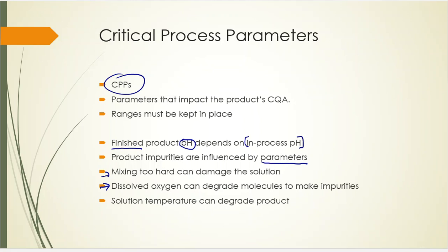And the reason is because that DO, that dissolved oxygen, can actually react with some of these APIs that we are after. And that DO, if it reacts with the API, can inactivate it, or it can create impurities because it's destroying things that are present. And I don't want those impurities, and I don't want a deactivated form of an API because it's not going to do its job that it's intended to do. So DO levels, very important.